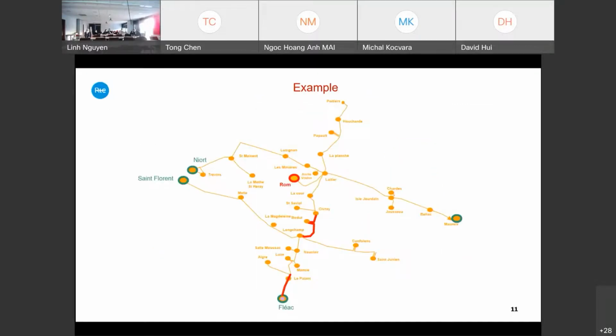Imagine that here you have a major congestion on this small line. For some reason, this line capacity is half of all the other ones. Imagine that you have a major congestion here because of some flow coming from south to north. Then, if you open this line, it solves everything. That's really the good thing to do in some cases. To simply switch off, and then the major flow coming from Spain to northern France will stay on the 200 kV, 400 kV grid, and will not come through this 90 kV grid.